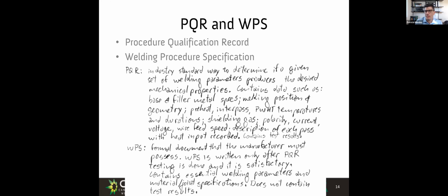But in welding, we do. Because if the bridge falls, we engineers have to say, look, I recommended we weld it this way for these reasons, and here are the tests we did. You record what welds were done, in what material, in what conditions, and you do whatever test you need to qualify, bend test, tensile test, or hardness, whatever it is.